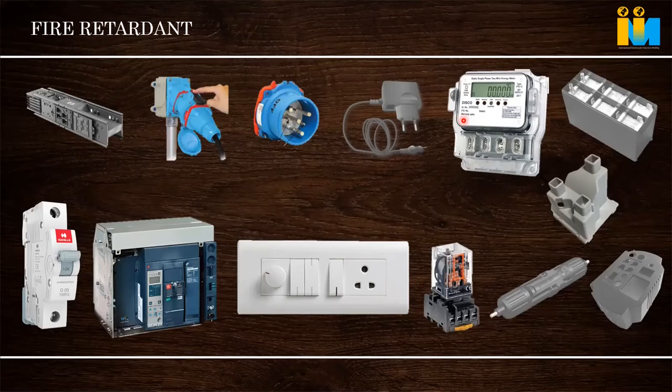And very few materials are there. There are materials which are V0 at 1.5 mm or 1 mm in transparent also, but they are very costly because of the technology. Because the moment we add fire retardant, it loses its transparency. Normally they use specific fire retardants which are very costly. That's why those materials are very costly, and there is a chance of a little bit of increase in brittleness also.